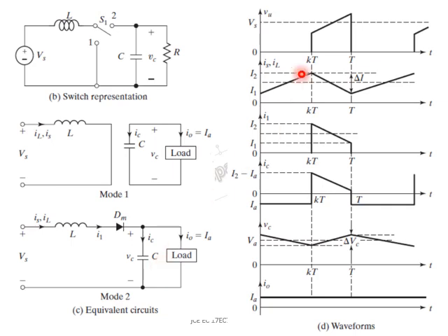During that time the input voltage is also connected to the load, so we show the voltage as this kind of voltage. And then what happens to the inductor current? The inductor current is going to discharge through the load. Now it is no longer charging, but it is discharging its energy. So the current falls from I2 to I1 in this case.